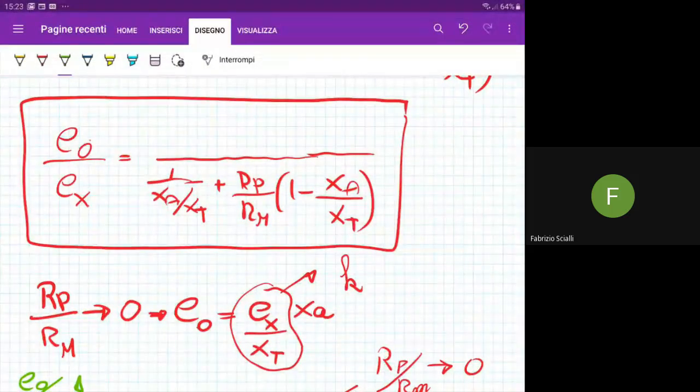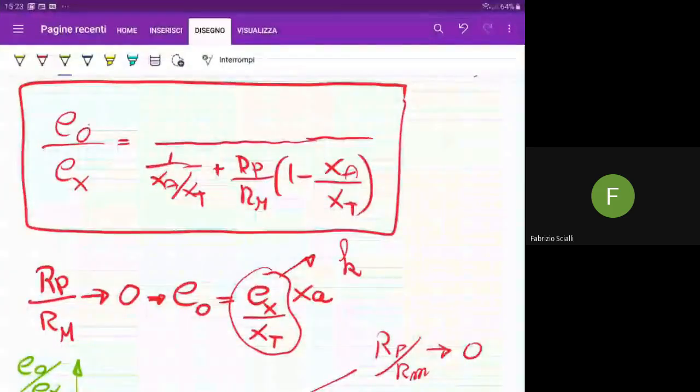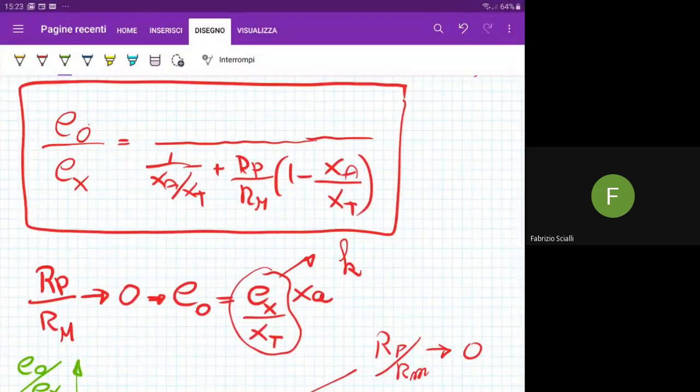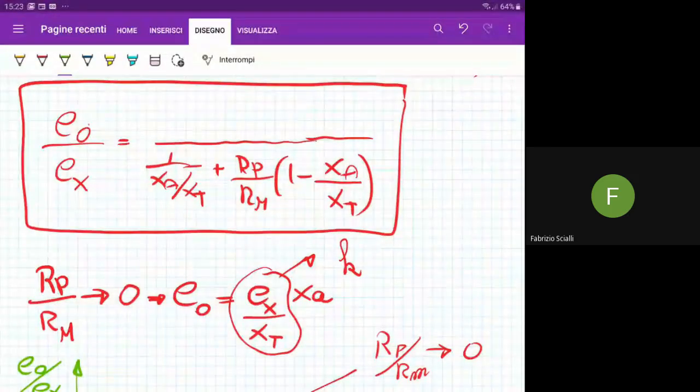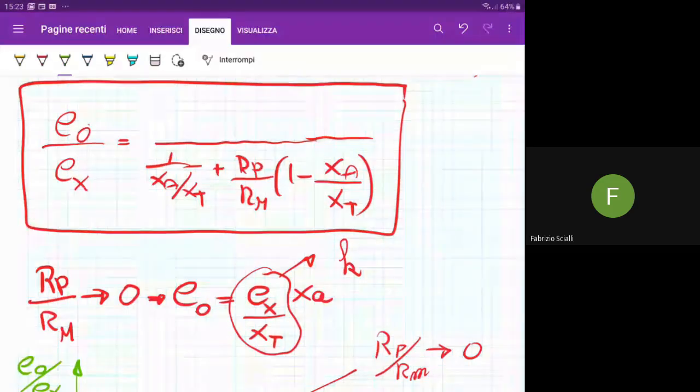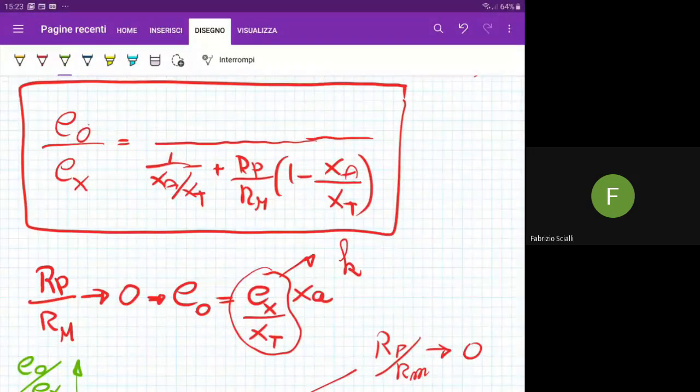It is nonlinear. That means that there is not a linear relation between the measured output tension and the unknown actual displacement. It depends on many parameters. There is not just one K, which is typical when you have a nice measuring device from this point of view. However, the equation is a zero order equation from the time domain differentiation point of view.